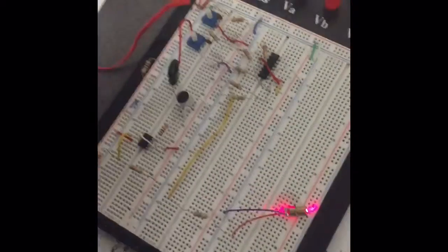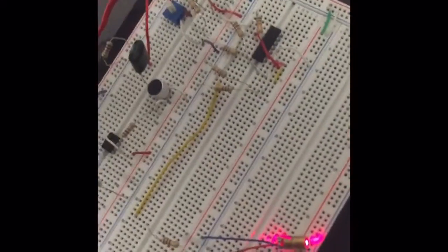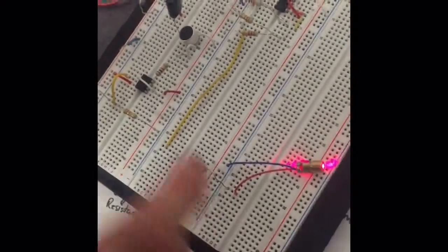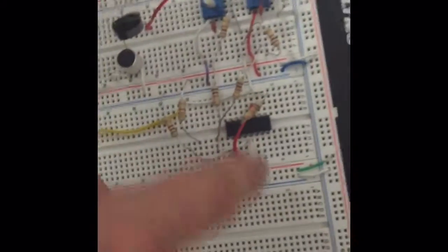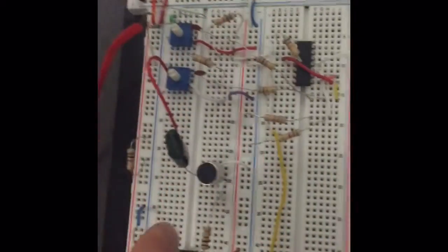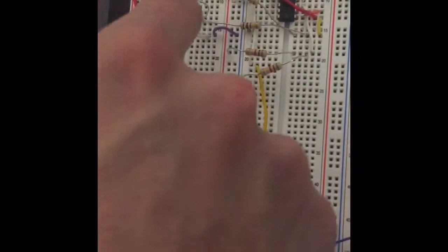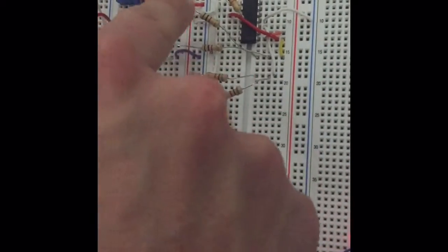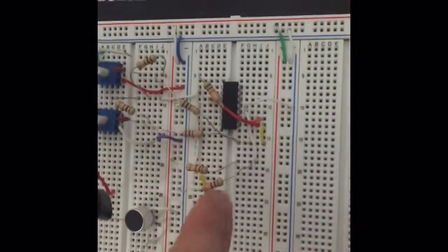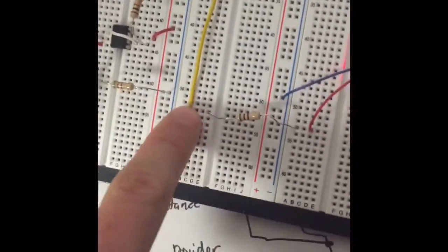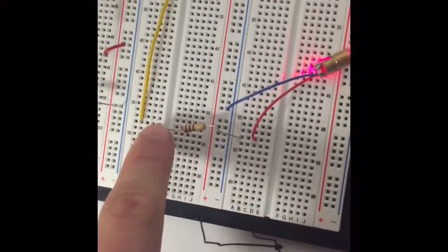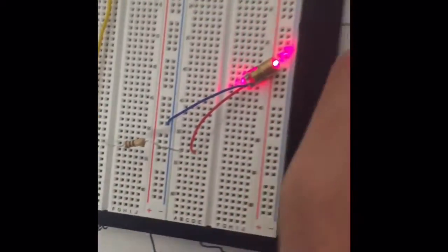All right, so this is our circuit. Briefly going to go over parts of the schematic that were on here. This is one of the voltage dividers. The other one is using the bottom corner of this op amp. Our AC signal from our iPod will come in through here. From the mic, it comes in through here. They add up at this node, go through this operational amplifier, come down this yellow wire with the output, and they will go through this and then out our laser.